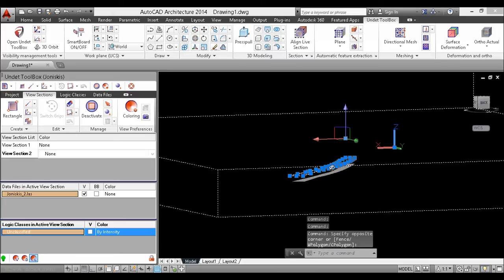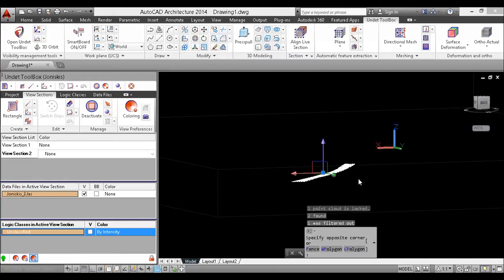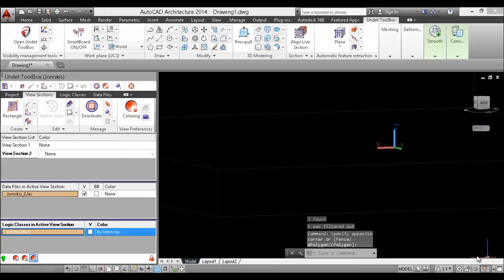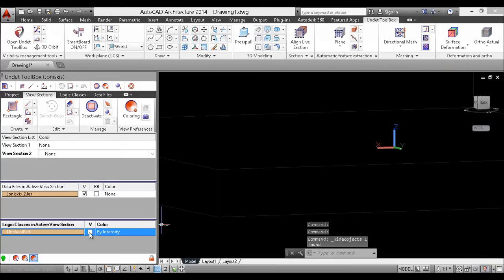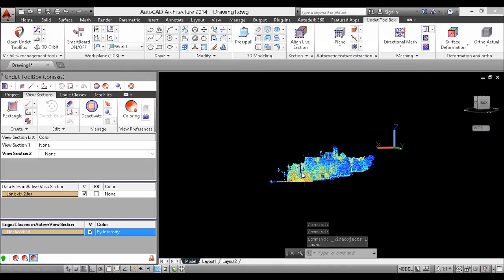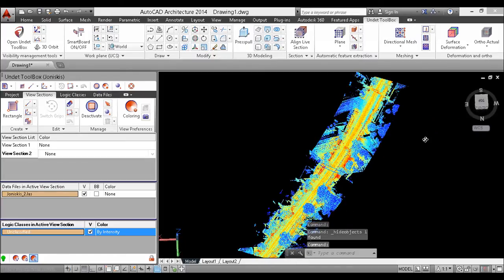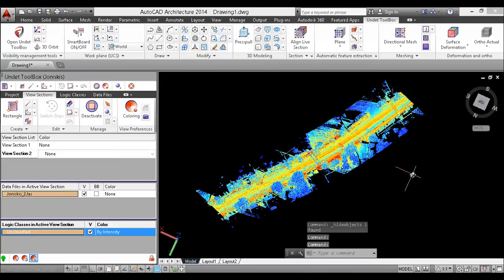Alright, let's delete the polyline. Let's hide the mesh for a moment. Now let's say that I want to create multiple sections of this mesh, multiple sections of the road. You could use this mesh in Civil 3D as a native civil object, as a civil surface, if you explode it into faces. Then Civil 3D will recognize it as a native civil object. But if you do not have Civil 3D, you can create multiple sections of the road over here as well.